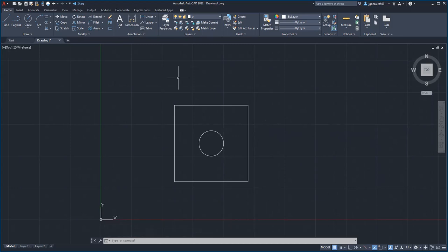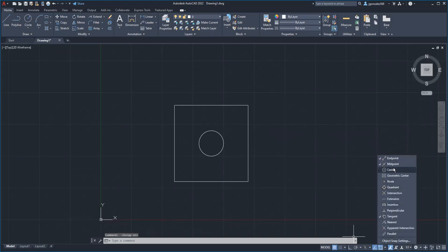Now, before we go any further, I want to make sure you turn off your snap. Turn off polar tracking, this guy right here, down here. For your cursor snap, turn it on, but only have endpoint, midpoint, and tangent. Turn everything else off.